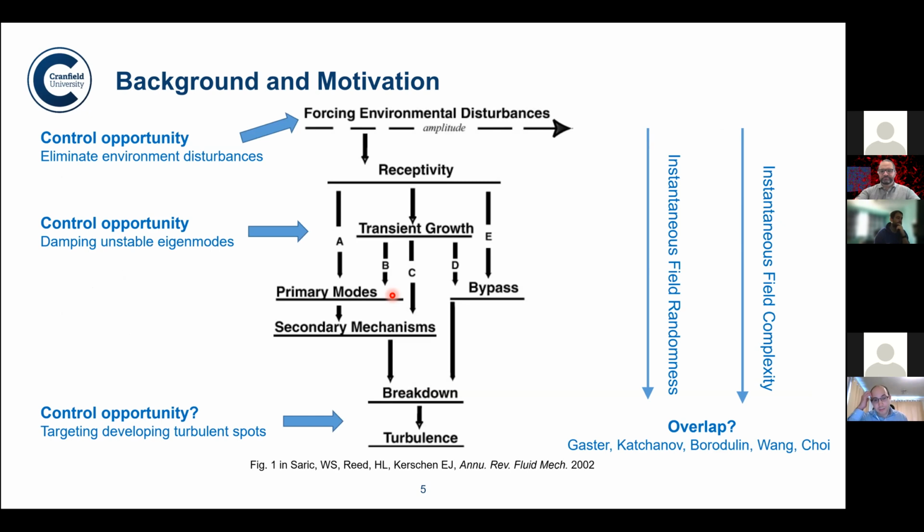One interesting idea is that transitional flow tends to start off simple, and even the initial stages of instability development, certainly the linear part, tend to be very reproducible and predictable. So there must be a point, usually towards the later stages of transition, where that reproducibility and predictability is lost.